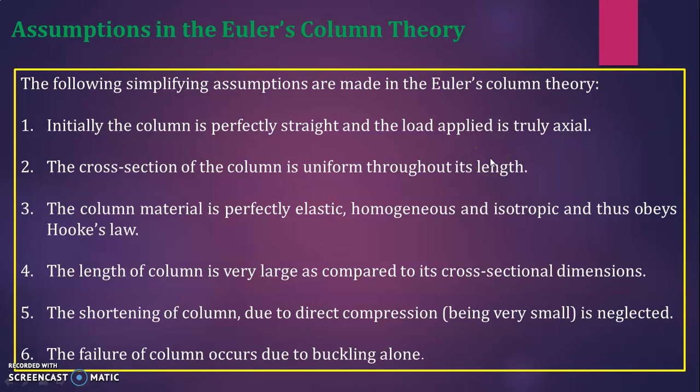Mainly, the column is perfectly straight and the load applied is axial. Then the cross section of the column is uniform throughout its length, and the column material is perfectly elastic, homogeneous and isotropic.